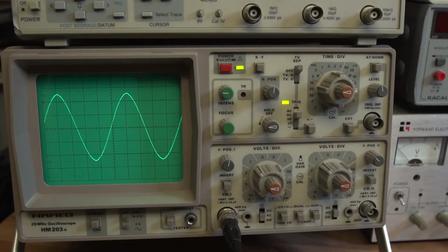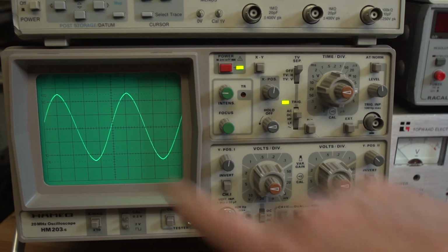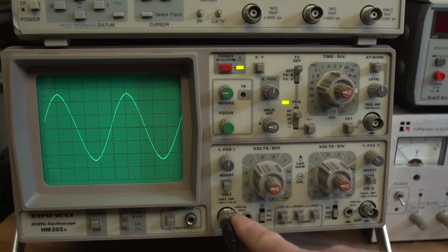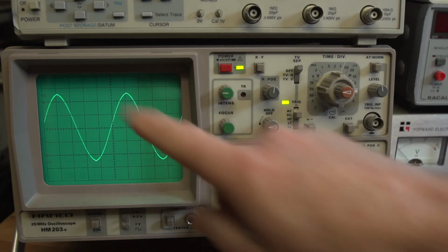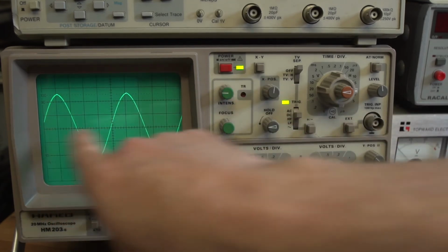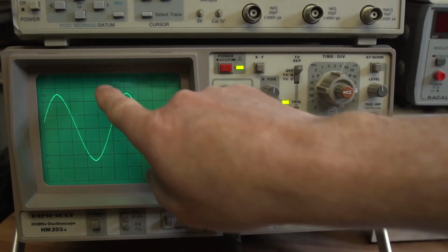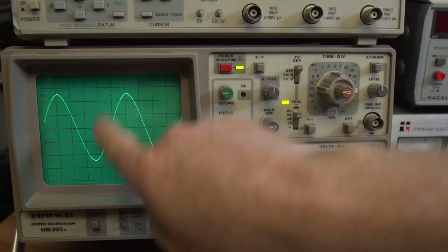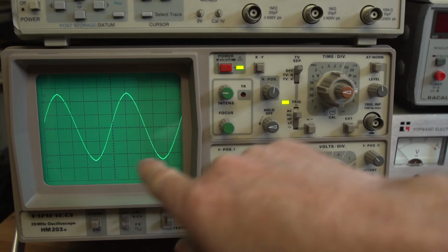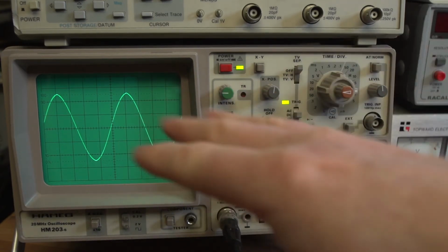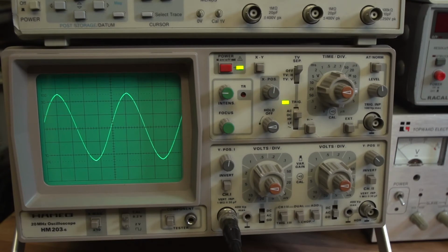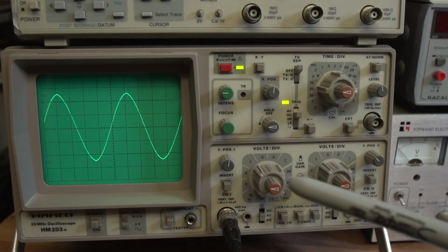Another aspect of oscilloscopes worth mentioning is the bandwidth capability of the Y amp, or of the input of the oscilloscope. So as you can see, the signal's coming in right now through the BNC input here, and it's our 100 kilohertz signal, sine wave, and we already know the frequency from the time divisions, and also the amplitude from the vertical axis, the Y axis here. So we've already done all that, but this is all well and good at 100 kilohertz. It's well within the oscilloscope's capability.